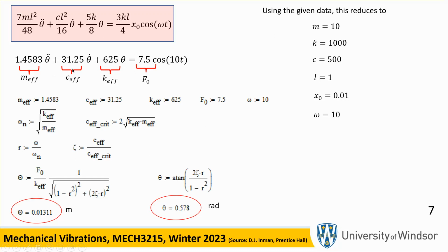we have the solution to this thing. Please go ahead and look at your notes for the steady state solution to that, okay? Now, we didn't have theta, we had x double dot, x dot, and x. Every time you see an x, replace it with theta, okay? So when you do that, this formula that we have seen many, many times, it said big X equal to F naught over K, okay? Now, we don't have big X, it's everything in terms of theta, so it's big theta, the amplitude of oscillation. That's exactly the thing that we want to actually calculate.